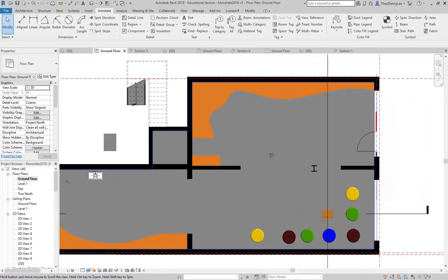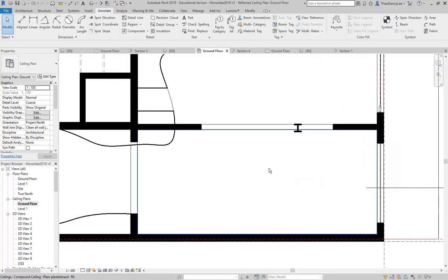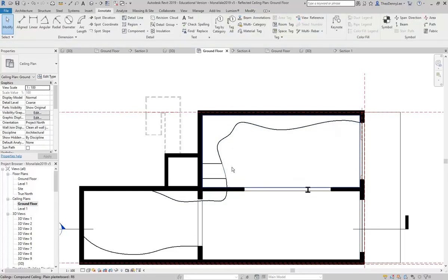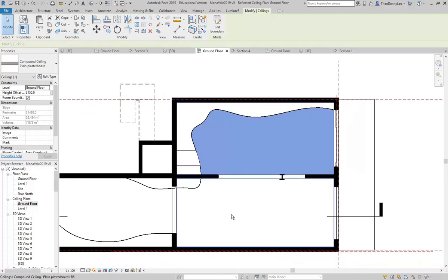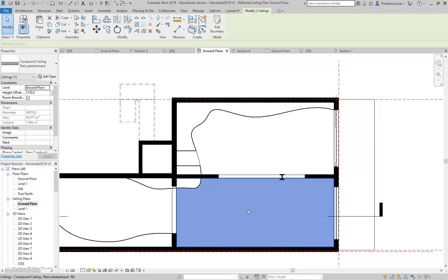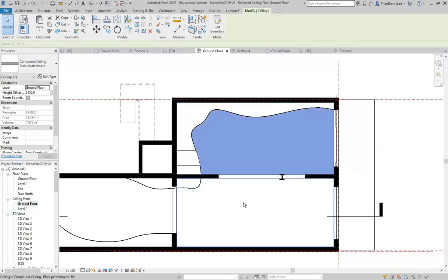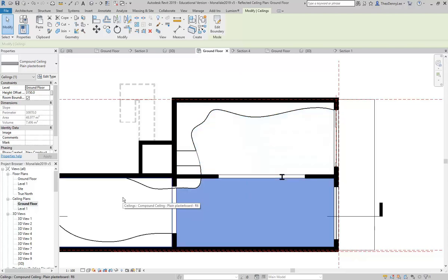Okay, so I've got the ceilings sorted out now, and it's actually really important to check what I was checking as well. When you have overlapping ceilings, you'll see that you can put the lights in, but then they'll usually get blocked by the other ceiling, and so you won't get any light when you render. So watch out for that. When you see that you've got a light and then it doesn't seem to be rendering or giving you any light in your render, that's one of the first things to check, that you may have extra ceilings.